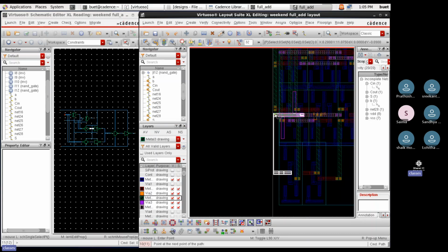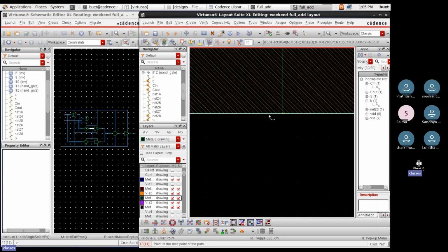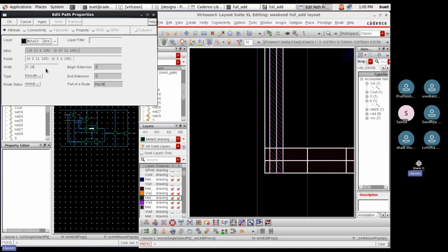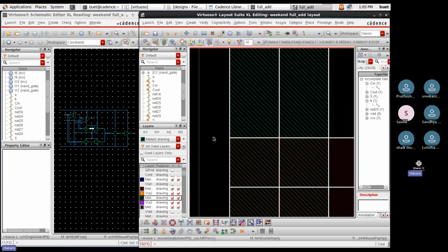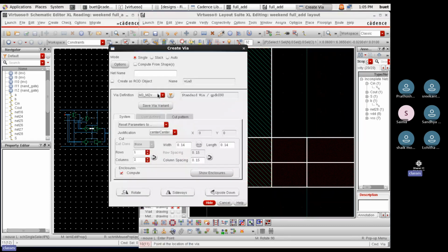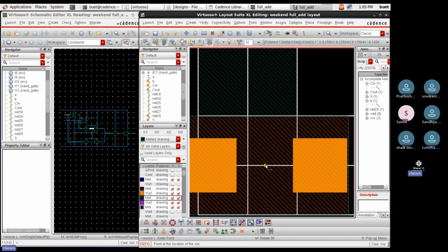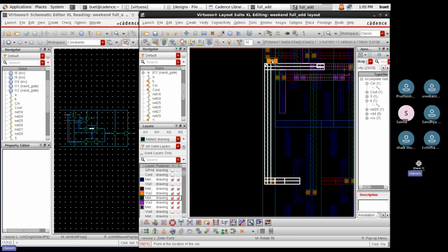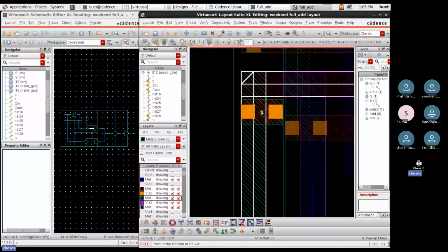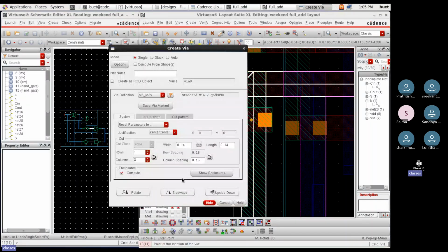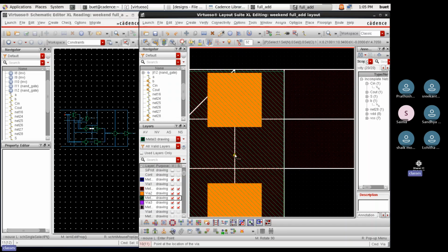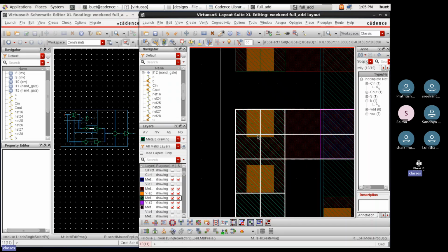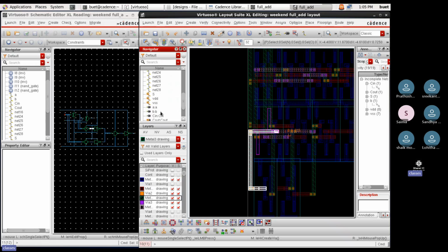And again, I will be taking one M3 track up till this level. And I will be making it as 0.26 micrometer. And I will be aligning this one with this one again. And I will be putting M2 to M3 via again here. One via here and one via, again I have to rotate this one. So two rotations happened in this one. I could have planned it in some other way. Then rotation wouldn't have come. So no issue. Okay, so up till here it is done.